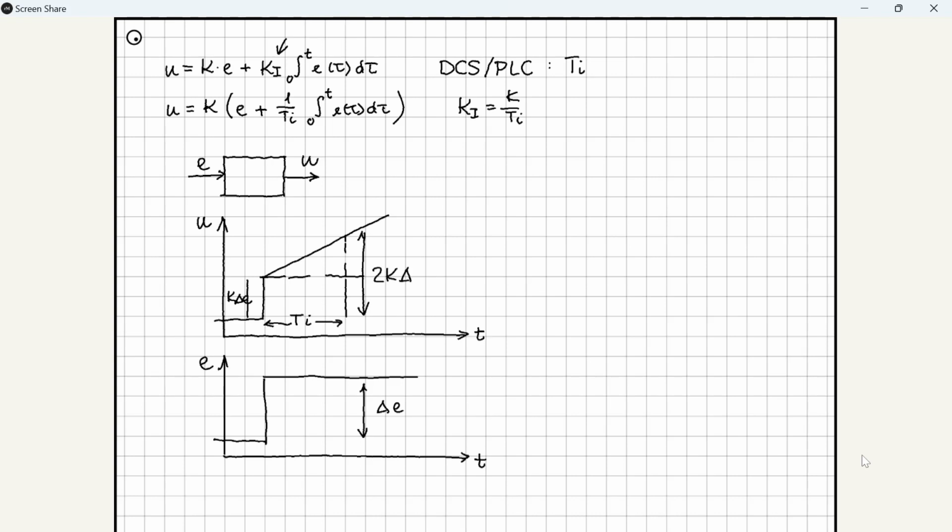If the process is fast, we want this doubling to be done quickly, while a slow process requires the controller output to change more slowly. In other words, the integral time should be chosen proportionally to the dead time or time constant of the process. The integral time has the dimension time, and the unit is usually seconds or minutes.